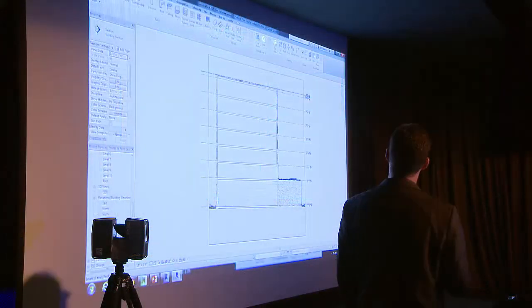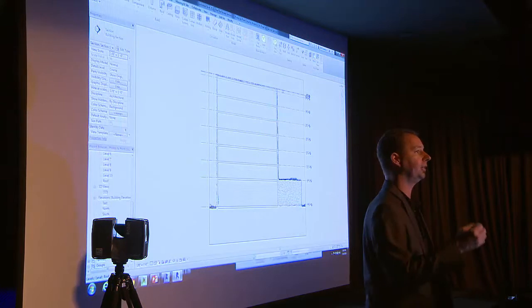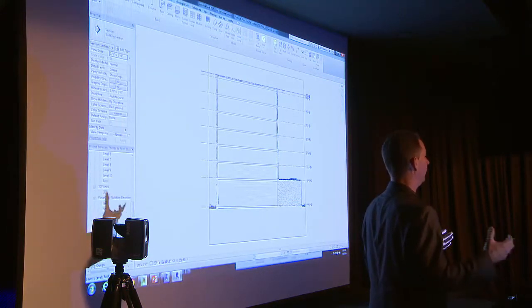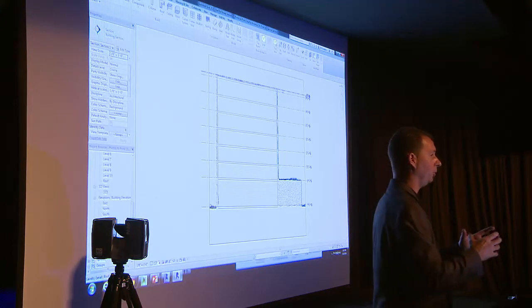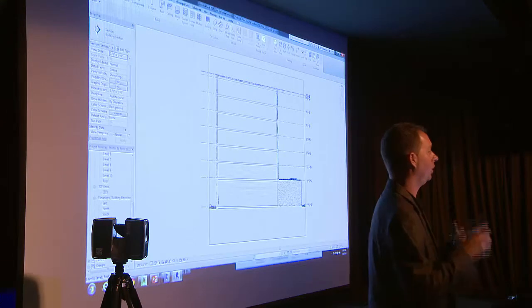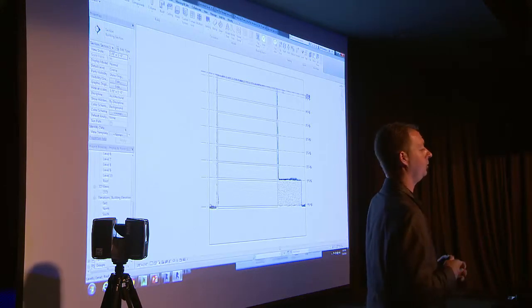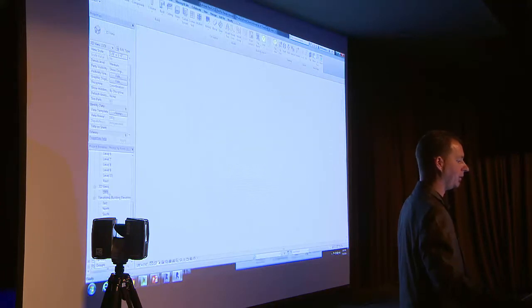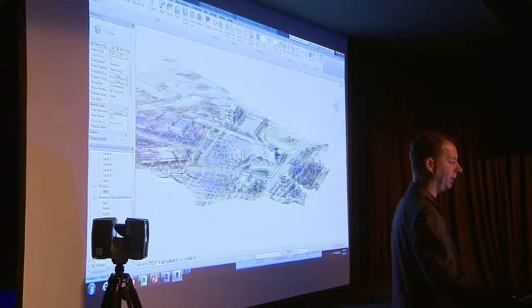The other big tip I can give you when working with Scan to BIM, narrow down the data. Don't work with the whole building. Don't work with the whole thing. You're not drawing the whole thing at once. Go in there and just narrow down one room. Narrow down just the exterior walls. Export the data so it's usable for each person for what they're doing with it. It makes a huge, huge difference to do that information while you're inside of Revit. Get better response, better quality, better data out as well there.